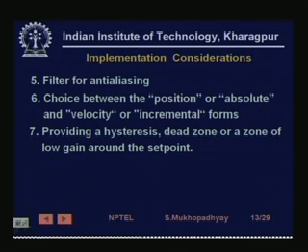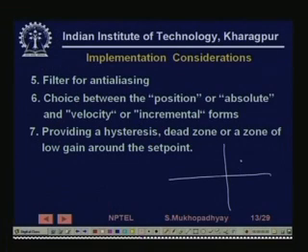Typically, as we have learnt in electronics also, suppose comparators. If you have ideal comparators, then the output will keep on switching, right. Therefore, we put either a hysteresis or a small dead zone around the 0 point. So, we say that if the error is a little bit here within this zone, then I am going to keep my control output as before.